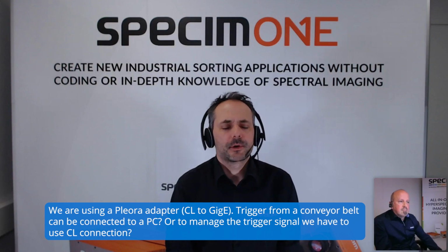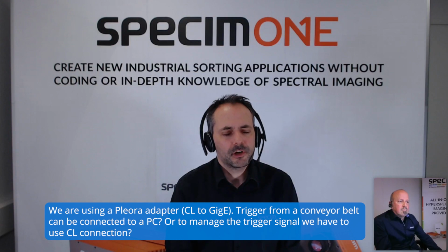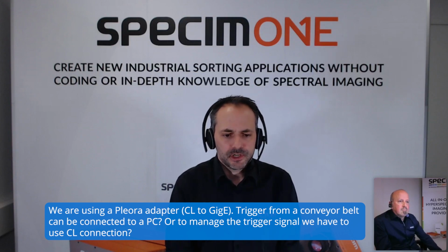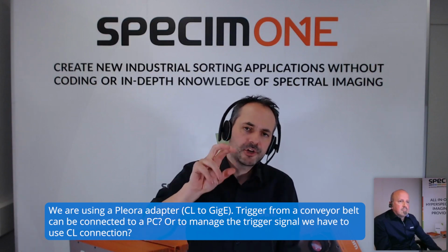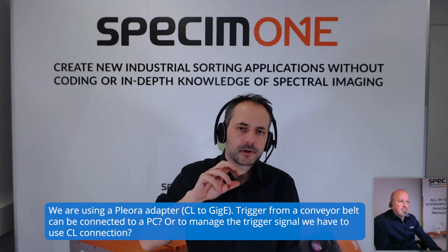Okay. So here it comes with the triggering of our cameras, basically. There are two ways of doing it. With our camera, it can be done via the power connection. We have the connection with our camera, and it has multiple cables in there, and two of them can actually be used for external triggering. It could also be used for strobing, so the camera can also generate a signal to trigger some other instruments. And the camera link cameras also have the possibility to be triggered via the camera link cable, via the grabber. So you have the possibility to do that.